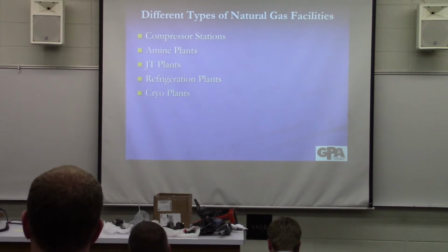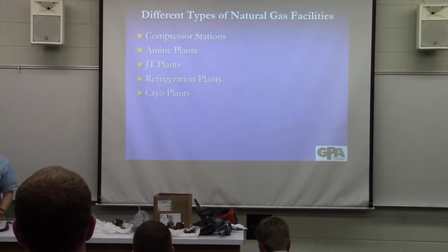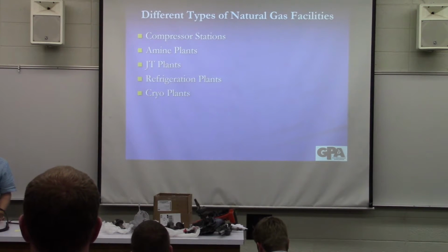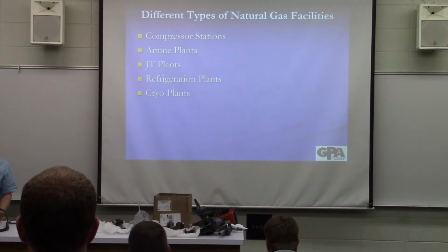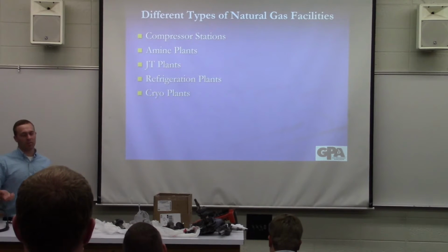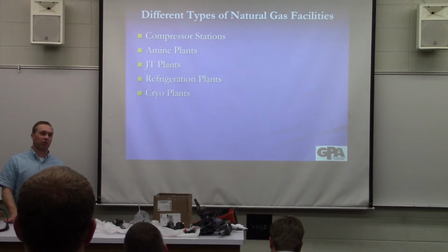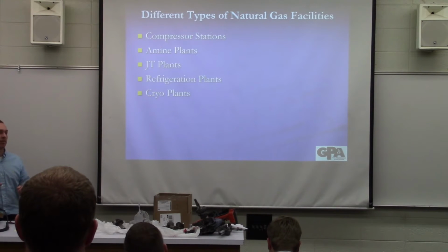So it's a simple expansion. There you go. I didn't know that when I graduated from BYU, but I probably did at one point for a test and then immediately forgot it. But the Joule Thomson effect is you do a simple expansion. And how do you do a simple expansion? Nozzle valve, right? So across a valve. You take a pressure drop across a valve and it gets colder.